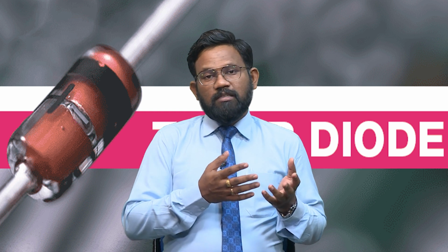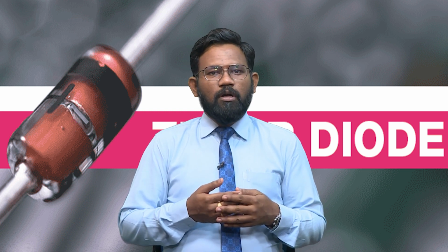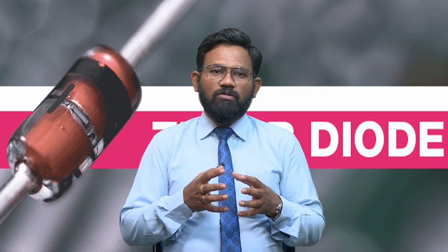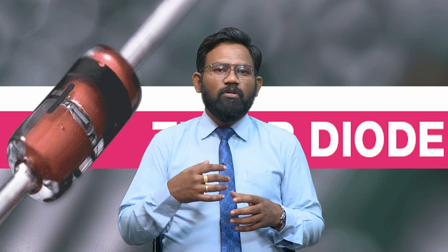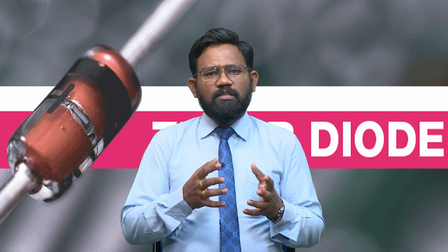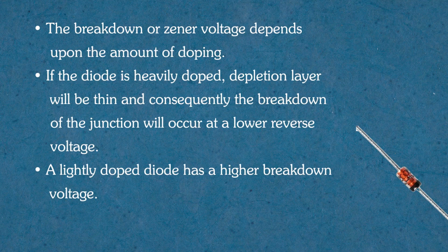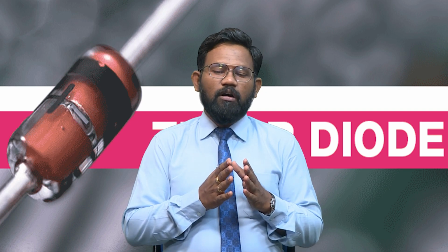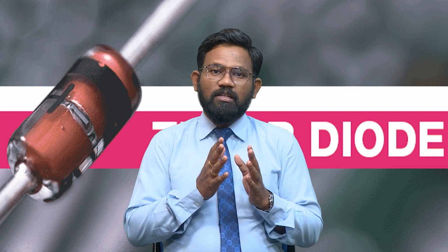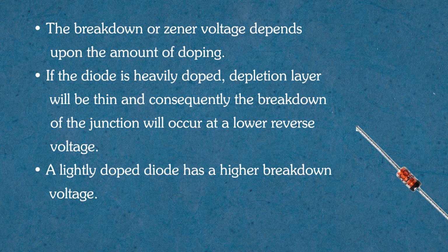We have discussed during the PN junction diode also, the doping plays a very important role. So the breakdown or the Zener voltage also depends upon the amount of doping. More the amount of doping, the lower the breakdown voltage will be, and vice versa also. So if the diode is heavily doped, the depletion layer will be thin. That means the thickness of the depletion layer depends upon the amount of doping. So if the diode is heavily doped, the thickness of the depletion layer will be thin, and consequently the breakdown of the junction will occur at a lower reverse voltage.